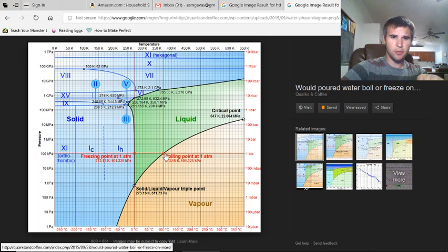We want to freeze the system, freeze everything down to this temperature, and then pull it down into a vacuum. But once we get it down into the deeper vacuum, then you can start applying heat, and all you're doing is further encouraging whatever is left as a solid to come out. As you apply the energy, you allow the phase change to happen. The heat provides the energy necessary for the phase change. Without the heat, you can't change phase.